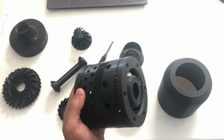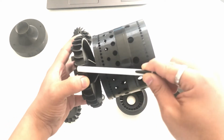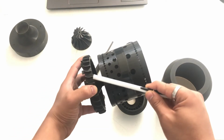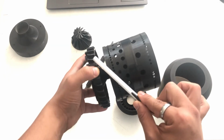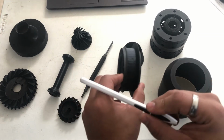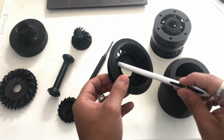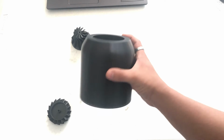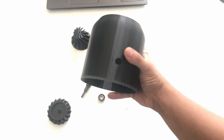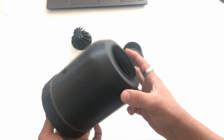Why this design? Because the air that arrives at a certain pressure is compressed, accelerating the air and generating a pressurized zone passing through the holes, guiding the oxygen and kerosene mixture towards the stator. The turbine stator. This piece redirects the mixture in a specific direction and the turbine starts to rotate. Turbine. With the mixture, the turbine generates thrust while it moves the compressor, making the engine self-sustaining. You can control the velocity depending on the amount of fuel that gets injected.